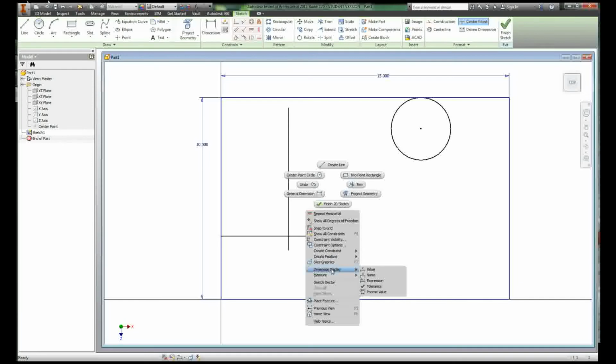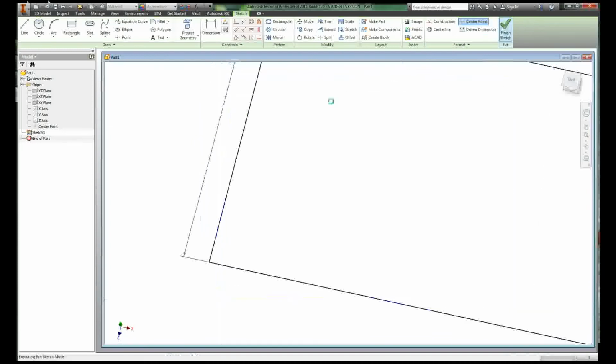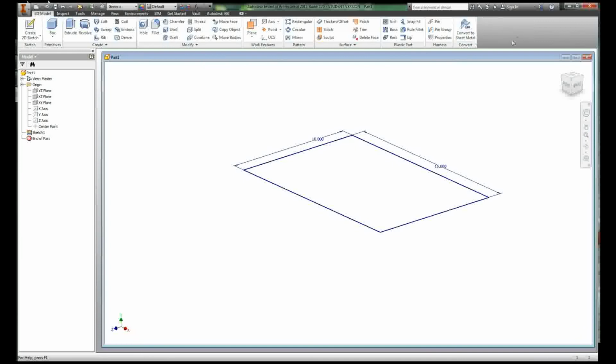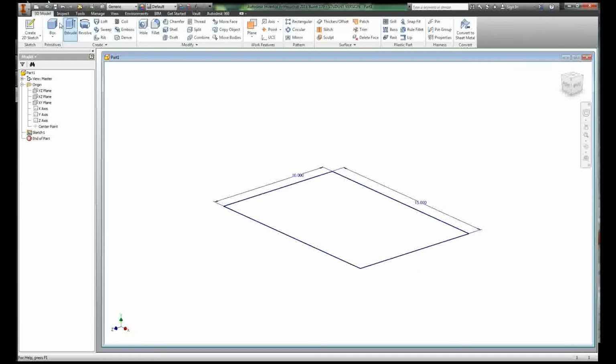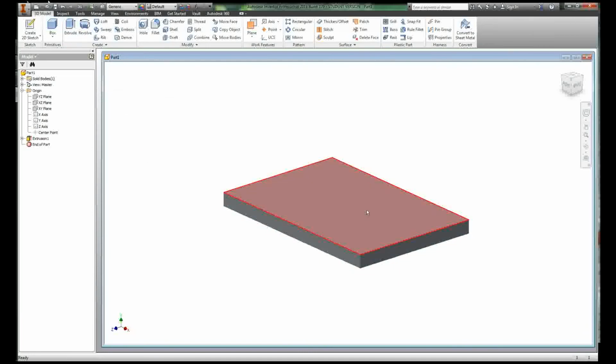It's something Inventor incorporated a couple years back to improve functionality. So when you're done with your sketch, you just hit Finish Sketch, which it was up here a second ago, and that'll bring you to the solid modeling, the 3D model view, where you can make things out of it. So I'm just going to do a simple extrusion that turns it into a 3D part.